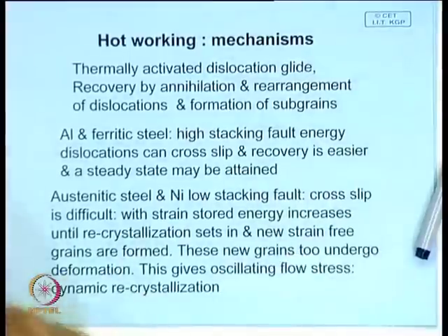Now, hot working is a thermally activated process, and here what happens is when you deform, there is slip taking place, and for slip to take place, dislocation movement is necessary. Dislocations are generated, but when this process takes place at high temperature, there is also a parallel process of dislocation annihilation, because dislocations get some added movement. A dislocation can climb, and by that they can rearrange themselves and try to occupy the minimum state of energy.